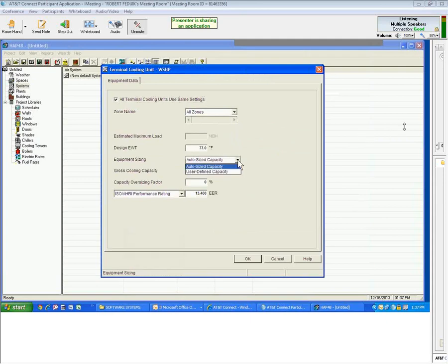your actual capacity that you want to model if you're running op costs, or you could have what's called auto size throughout HAP, which has become very popular. I don't know the size. You tell me the size I want to run an op cost, and I want to make that op cost minimally ASHRAE compliant. So auto size with minimal ASHRAE compliancy is very popular.